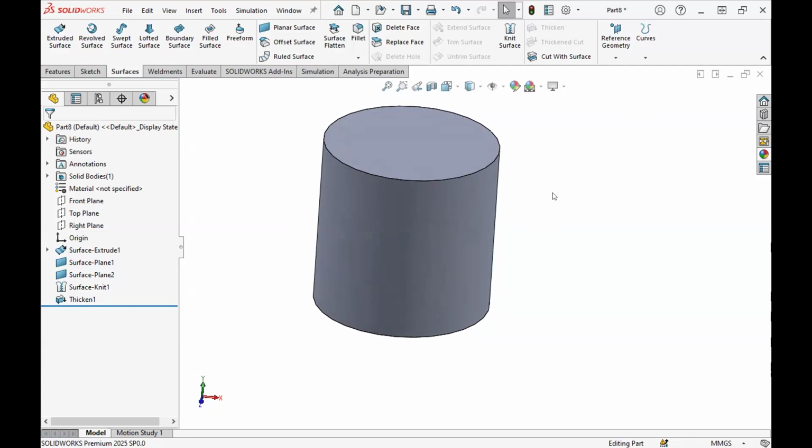to use surfacing sometimes. Under the hood, SolidWorks solid modeling is based off of surfaces. So when you're running a command and it fails for some reason, you may be able to get around that failure. Let's say you can't go back in the tree and fix whatever is causing it. You can get around that by using surfacing. So rather than making the whole cylinder in one single command, I can break it out into basically 5 separate commands and dive in a little bit deeper and see where that error might be happening and how I can address it, how I can fix it, how I can get around it.